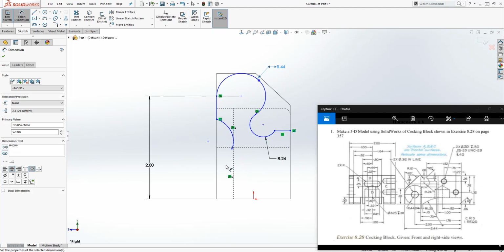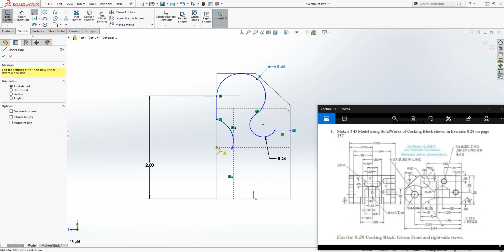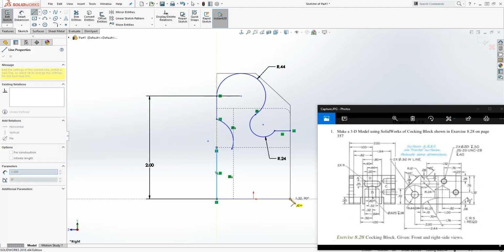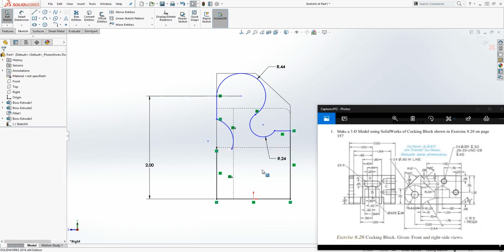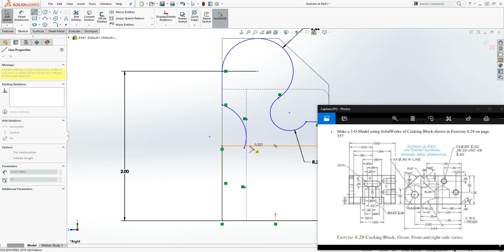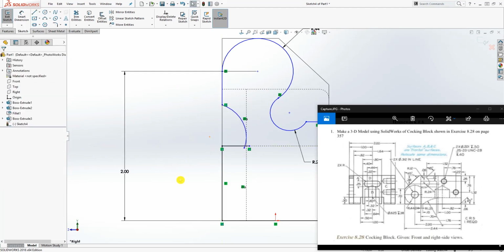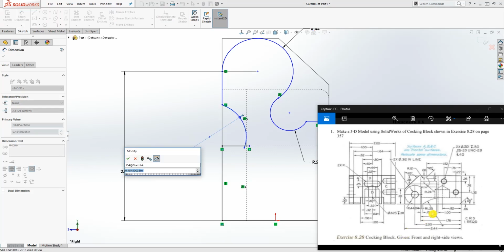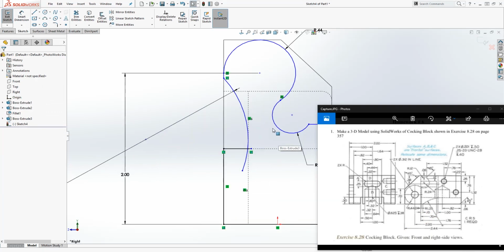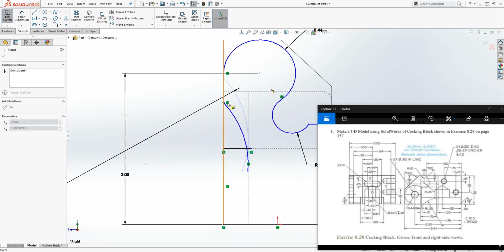Good. So the only thing we need now is, if you look over here, this comes there and it comes down and it comes back to that edge, because if you look over here, there's a hidden line on the back, which is this chamfer over here. So that's what we're going to do. We're going to draw a line from this point here up over there and make the line come up. So we have that, and all we need to do is add a radius to this. The radius is 1.25, and we're going to move that.